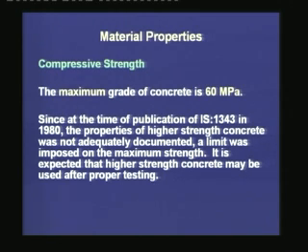But over these 2.5 decades, high strength concrete has been studied, and it is expected that it may be used for prestressed applications after proper testing. We have to be careful that the high strength concrete should meet the minimum requirements for prestressed applications. It should not have high shrinkage, the heat of hydration should not be excessive, and also it should not be brittle. If a high strength concrete satisfies these requirements, then it can be used for prestressed applications.